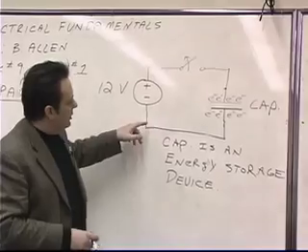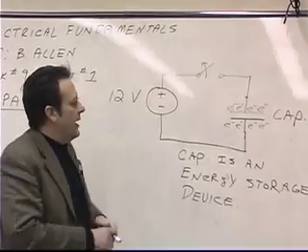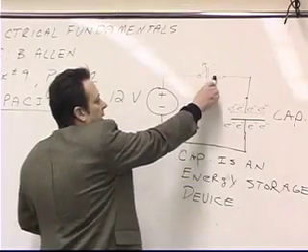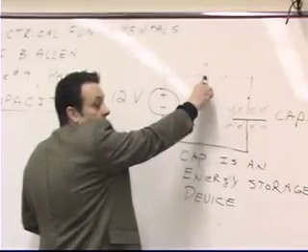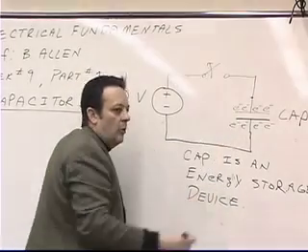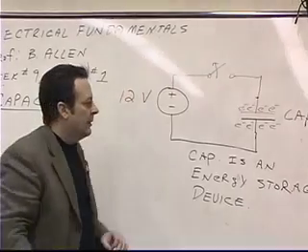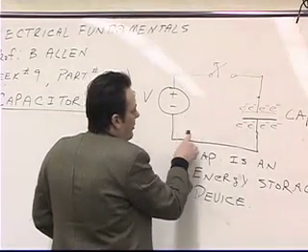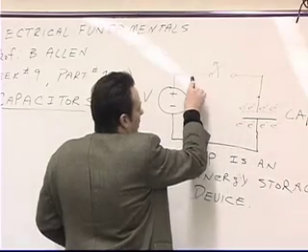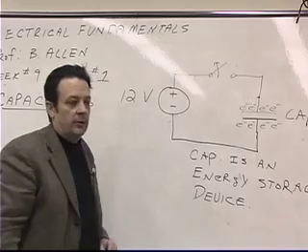Now, in this circuit right here, let's just take note of the fact that we have an open at this switch. So we would expect that how many amps are going to flow through that open? 0. No amps at all. So if we go around this loop, what we find is we don't have a closed loop because there's an open switch right there.